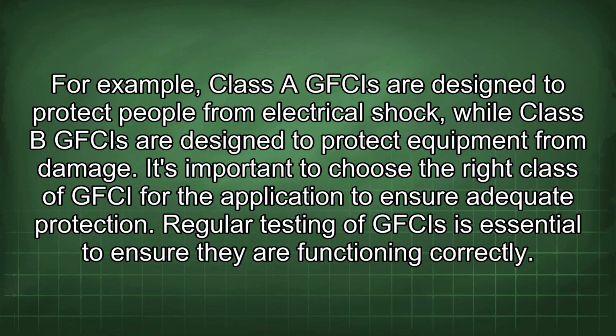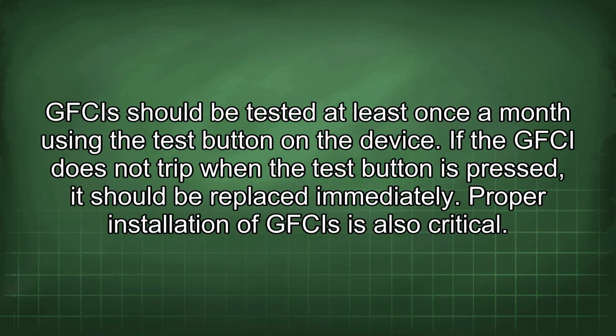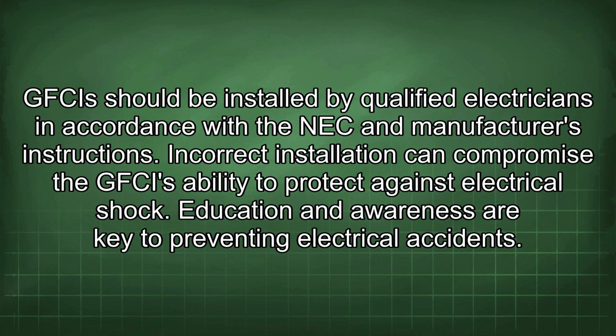Regular testing of GFCIs is essential to ensure they are functioning correctly. A GFCI should be tested at least once a month using the test button on the device. If the GFCI does not trip when the test button is pressed, it should be replaced immediately. Proper installation of GFCIs is also critical. GFCIs should be installed by qualified electricians in accordance with the NEC and manufacturer's instructions. Incorrect installation can compromise the GFCI's ability to protect against electrical shock.